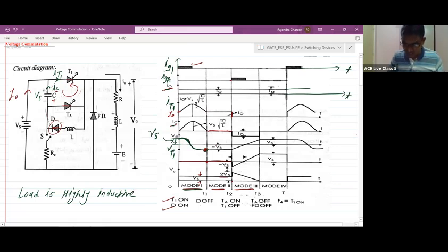So that's why thyristor T1 current becomes 0 suddenly. Now when the thyristor T1 current becomes 0, please try to understand, it means thyristor T1 will turn off. So when thyristor T1 turns off, what will happen? This capacitor will try to discharge through C, TA, load, and again Vs, and back to the C. In this loop, the capacitor goes on discharging.